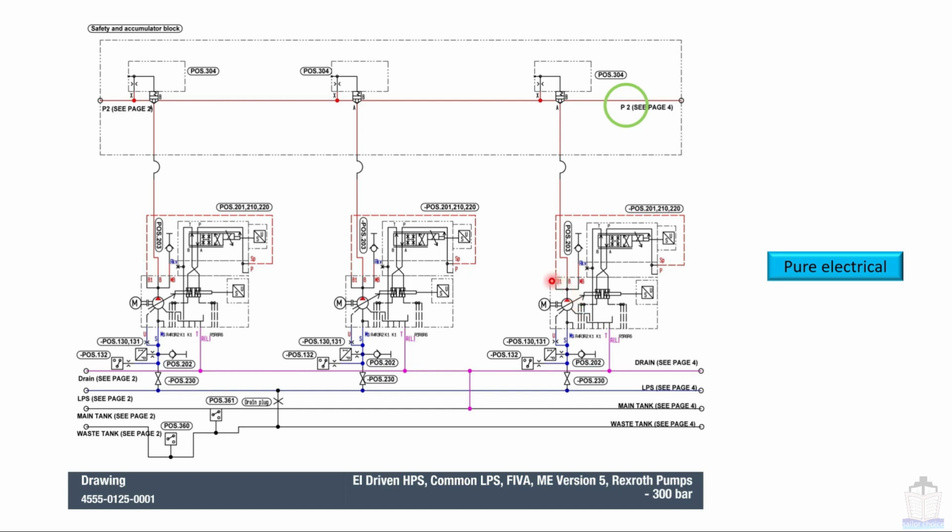You can see here that from point B1, one line comes and goes into the point SP. SP denotes the sensing point, which acts as feedback. This channel number 70's job is only to set the desired pressure, and with the help of this SP and B1 point, the swash plate pump maintains the desired pressure. I hope this is clear.